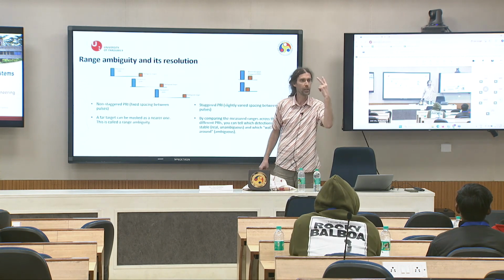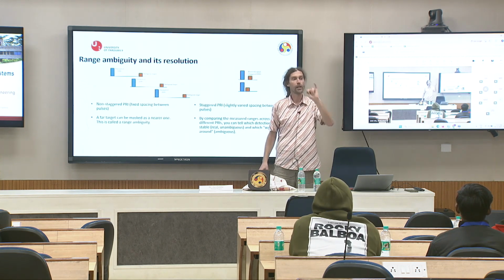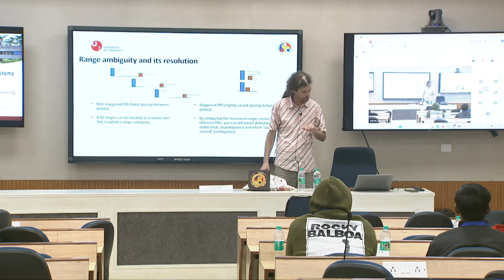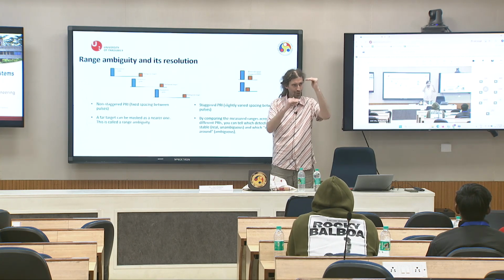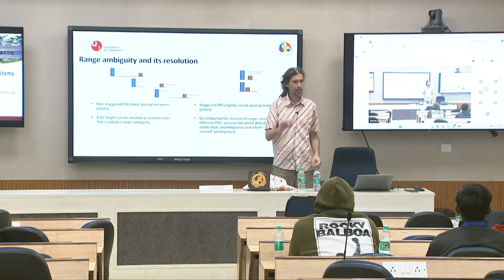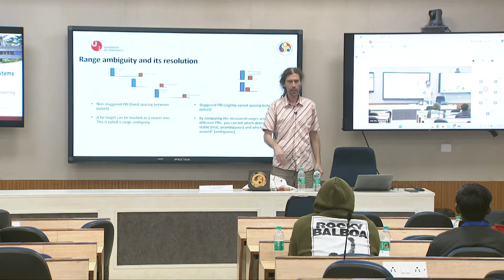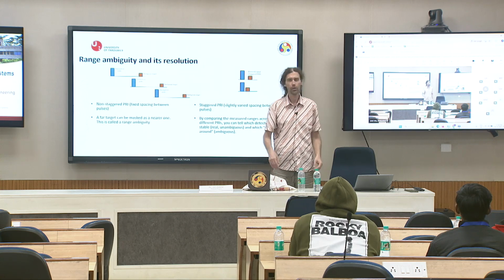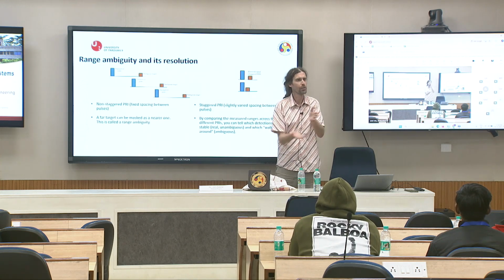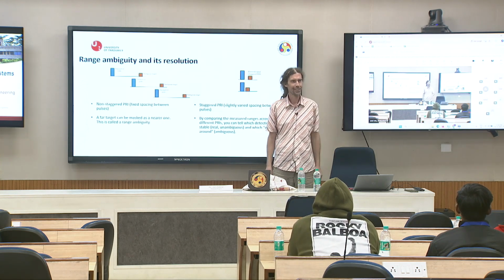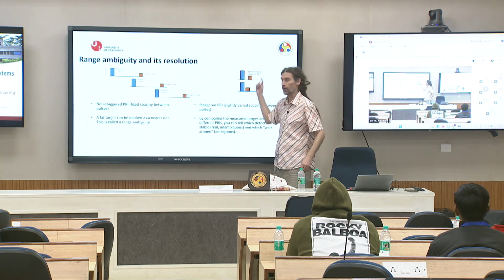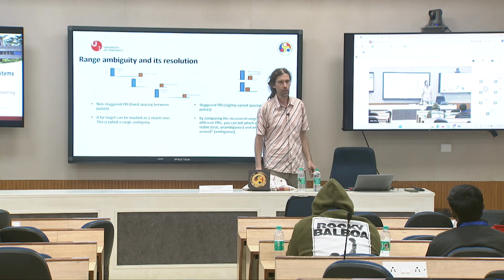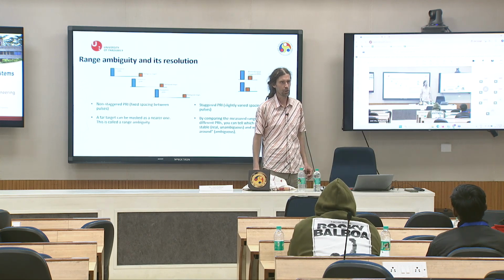So I have two bad values, but due to one equation I will show you later, we can solve this problem, and the result will be okay: my target is 60 kilometers far away, or some value that is correct. So it is so-called staggering, and it is used very often in almost all primary radar systems.